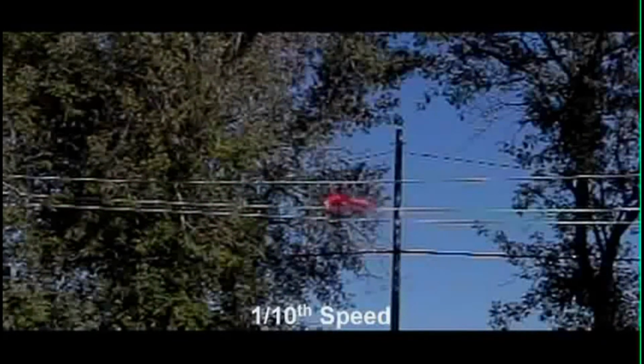And because we have the current flow through the arc, that creates a high magnetic field, and that makes the arc dance around. That's what makes the arc go flying down the line. If it goes phase to phase, it acts like a railgun, and the arc will really zip down at tens of feet per second down the line, which, depending on which direction you are from the arc, it can make it better or worse. The magnetic field really plays a big role in where the arc goes, if it gets bigger, and how fast it moves, and which direction it goes.